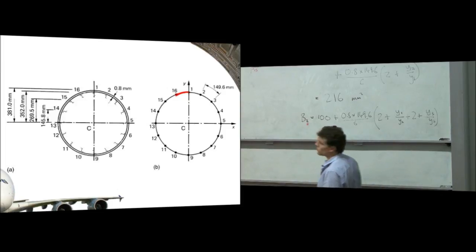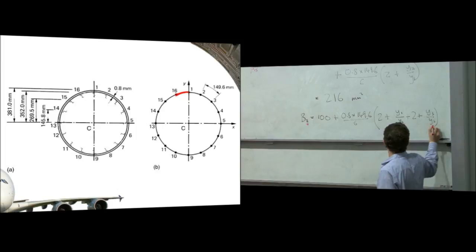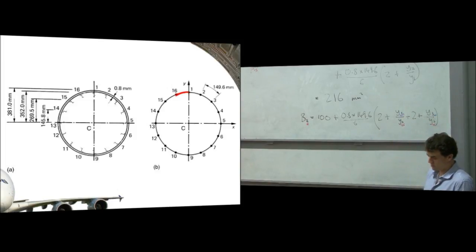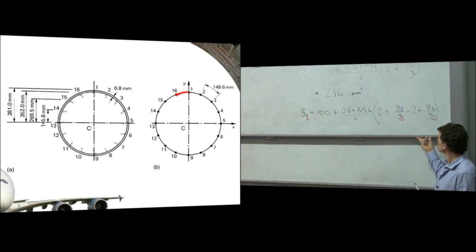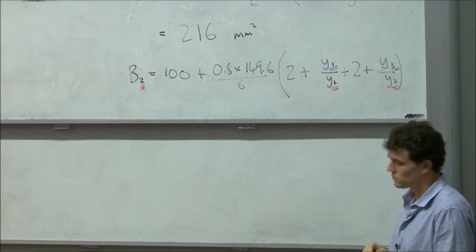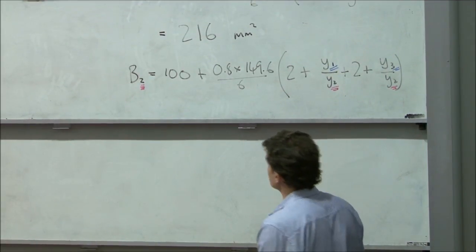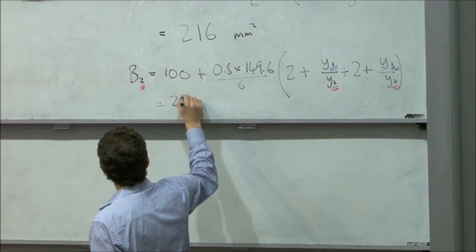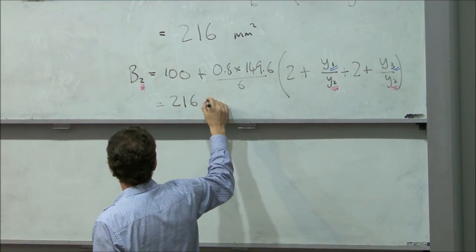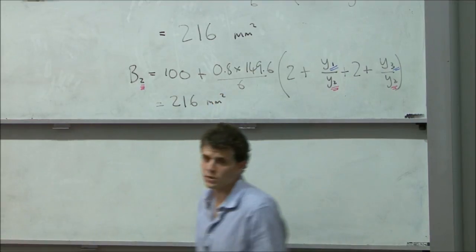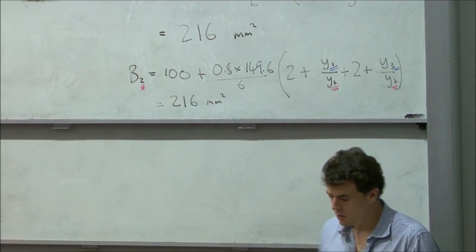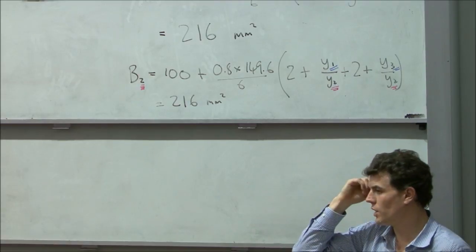So the boom we're trying to work out is always on the bottom here, and the neighbours are on the top. And this also should equal 216, or 216.6, I think, but 217. If you go around, you'll find out that they're all equal to 217.